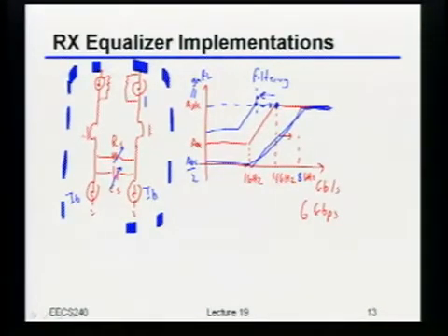So by the way, we've modified the transconductance. And gain, of course, is set by gm times RL. So what else can we modify? RL. Yeah, RL, right? So what we basically have to do is somehow make it so that RL also has a frequency dependence, right? So by the way, what kind of frequency dependence do we want RL to have? What do we want RL to look like? I should really say ZL, I suppose, to be precise.